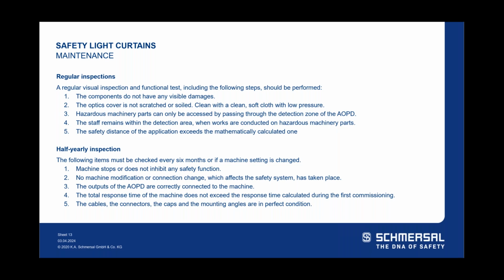Safety distance of the application exceeding the mathematically calculated one from the beginning. We talked about our safety distance. You know, has somebody come in and done work on that machine and moved it? And now all of a sudden, these light curtains are too close. So all things that we can regularly inspect.